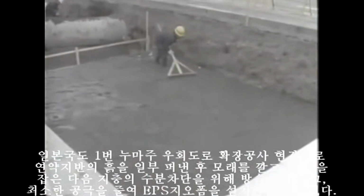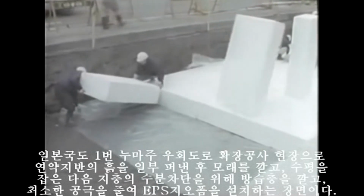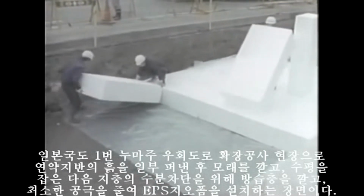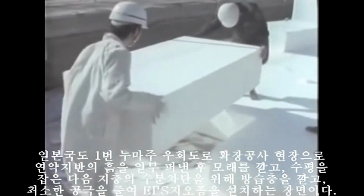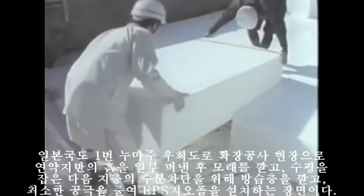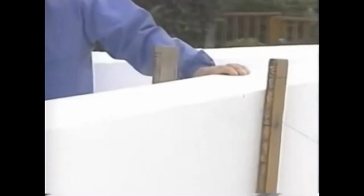On top of the sand, a vapor barrier is placed, and the EPS foam is positioned so that there will be no voids between the blocks. Cutting of the foam is easily accomplished with the use of heated wires.